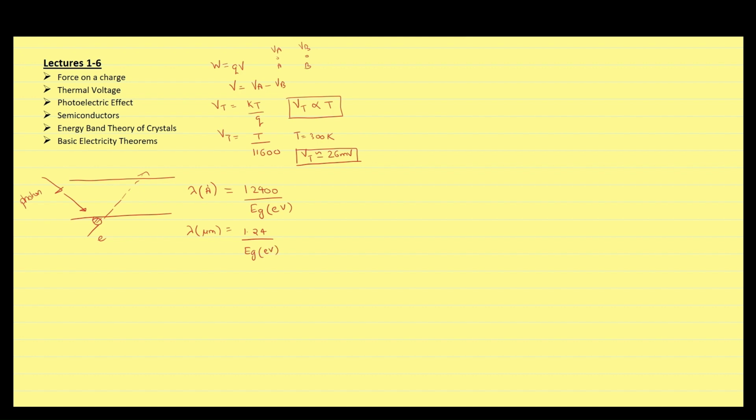We studied semiconductors and differentiated them from insulators and conductors. In the later chapters, when we were discussing non-degenerate semiconductors, we studied that if we dope an intrinsic semiconductor very heavily, then it behaves more like a metal. Also, at 0 Kelvin, semiconductors behave more like insulators. At normal temperature, say room temperature, the bandgap energy of an insulator is of the order of 6 electron volt, whereas for semiconductors, the bandgap energy is of the order of 1.5 electron volt. So it is much easier for a photon to knock out an electron in a semiconductor for making its transition to the conduction band. Therefore, its conductivity is far greater than insulators.